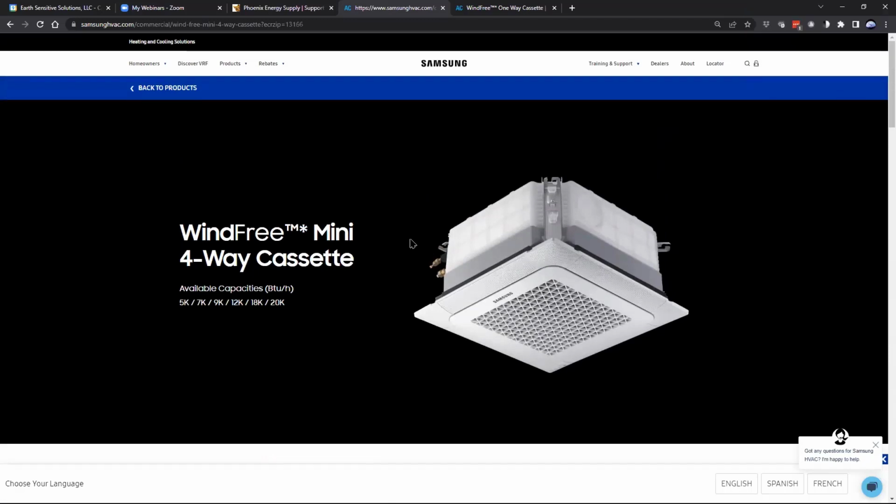So here's an idea. If we're talking about one of these cassettes, obviously we can't block the airflow, but could you build, I envision almost a wooden grate, a grid that can bolt up around it, behind it, but still open enough to allow airflow, so you don't really see the unit. Does that make sense? Yeah, we've definitely done that in the past, Matt. That's a great thought. We've used everything from decorative metal to wood that meets the Manual D and other calculation requirements for airflow and CFM. We've certainly done that, so we could think about something like that.